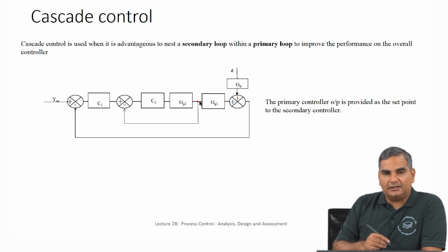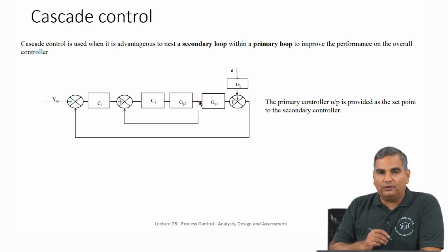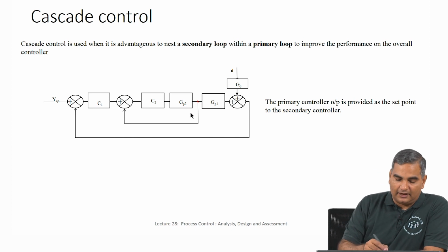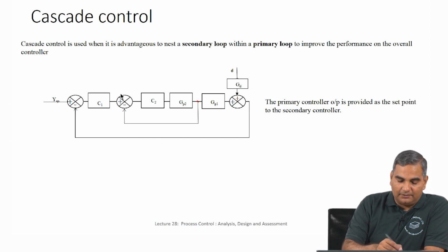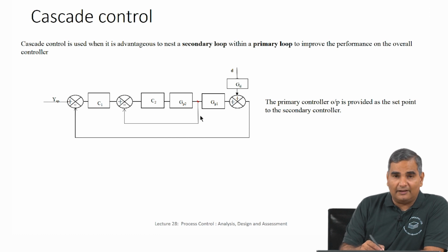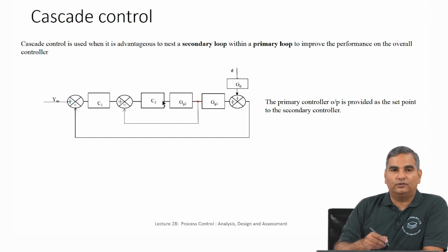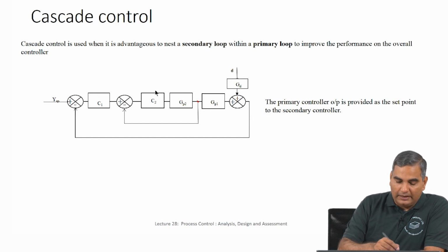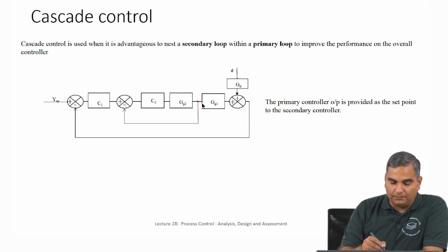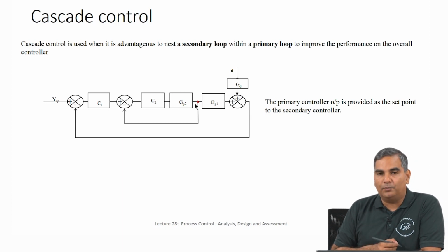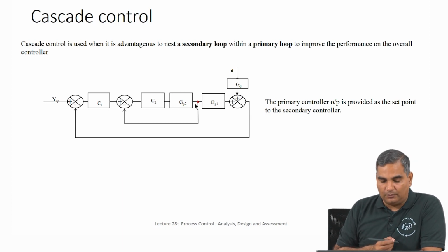But if I actually measured a stem position, then you can give a set point to the stem position and introduce another controller, so that this controller looks at the set point for the stem position, and now since I have a measurement, I can compare that measurement against the set point and then close the loop inside. Okay. So, there is one inside loop and another loop outside, and this inside loop is possible only if I am able to measure the output of the valve dynamics, which is the actual position.